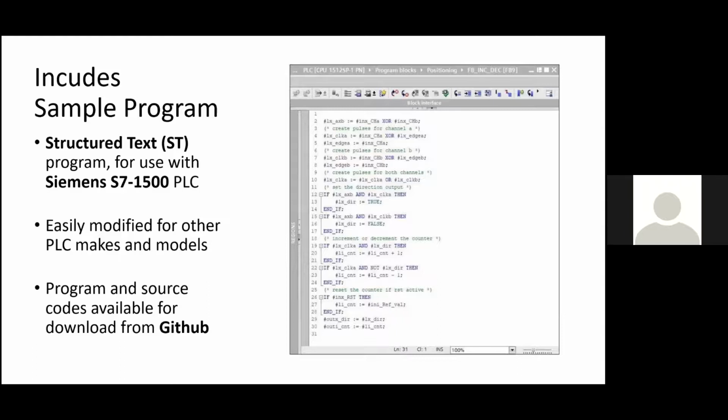Now, as with the first of the 24-volt models we're going to look at today, each of the workstations of the 24-volt variation of the Training Factory Industry 4.0 model has a relay board for motor polarity reversal and both the multi-pin connector, again 34 pins with a grid of 2.54 millimeters, along with PCB terminals with push-in connections for all inputs and outputs.